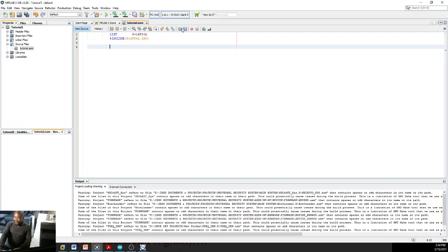Now, one other most important thing when writing a program is the beginning. The program doesn't just run randomly from any location. It has to start running from somewhere. For a PIC microcontroller, that is our reset vector. The program will always start to run from the reset vector, whether at power on, or when you reset the microcontroller using MCLR, or on a watchdog timer reset. Any form of reset, the microcontroller will start executing instructions at the reset vector. For the PIC16F84A, the reset vector is program memory location 0.